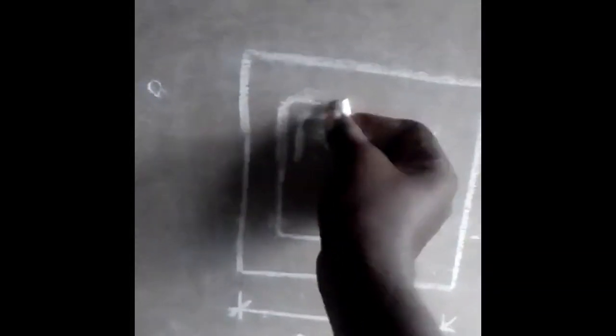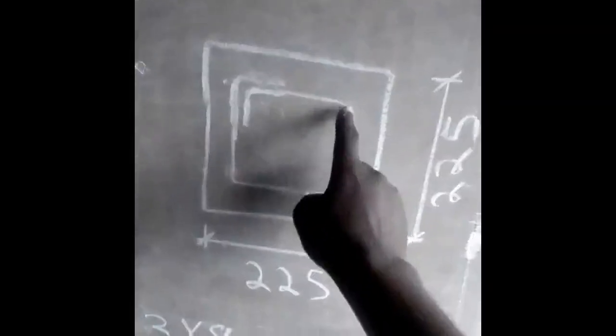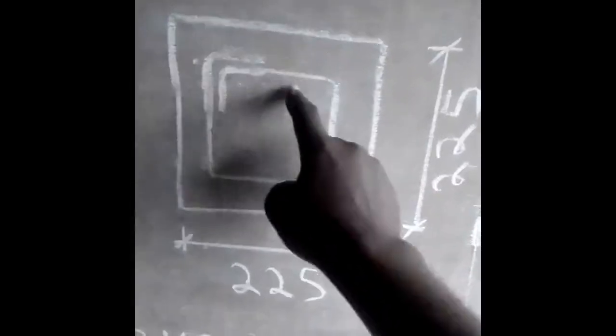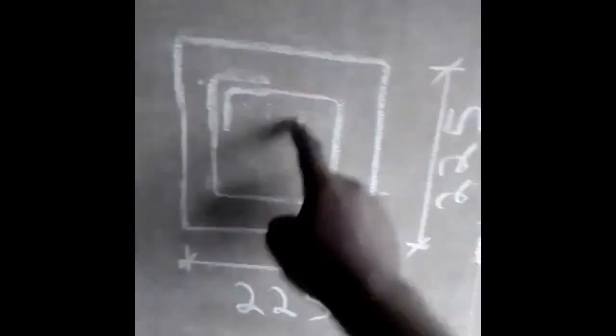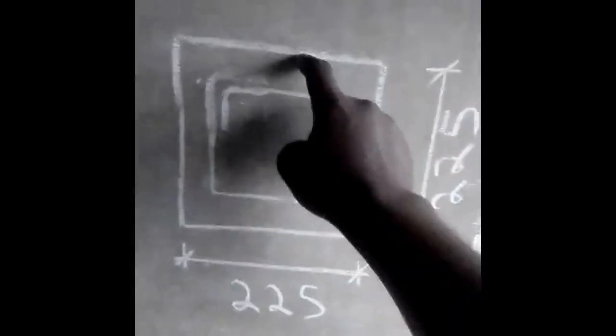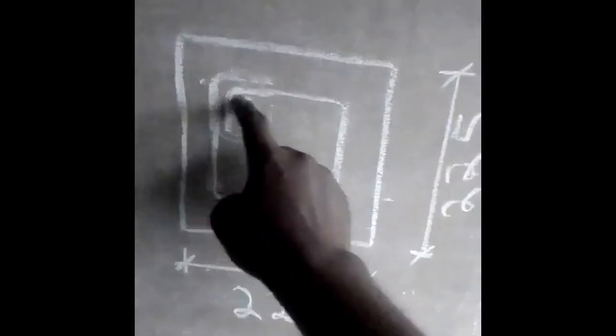In practice, I usually bend this place 100 millimeter, from here to here, which I call 4 inches. Then I need to give a gap of 1.5 inches on each side, so 9 inches minus 3 inches is 6 inches, which is 150. From here to here is 150. That's how I used to do mine.